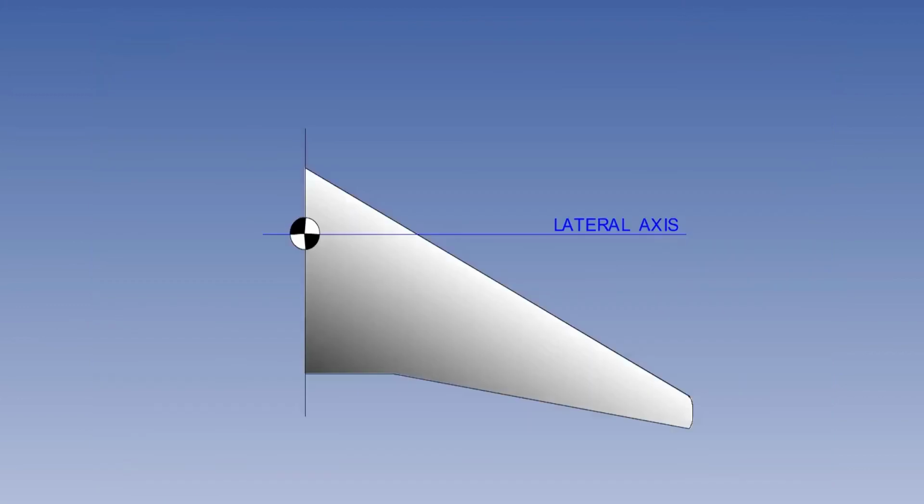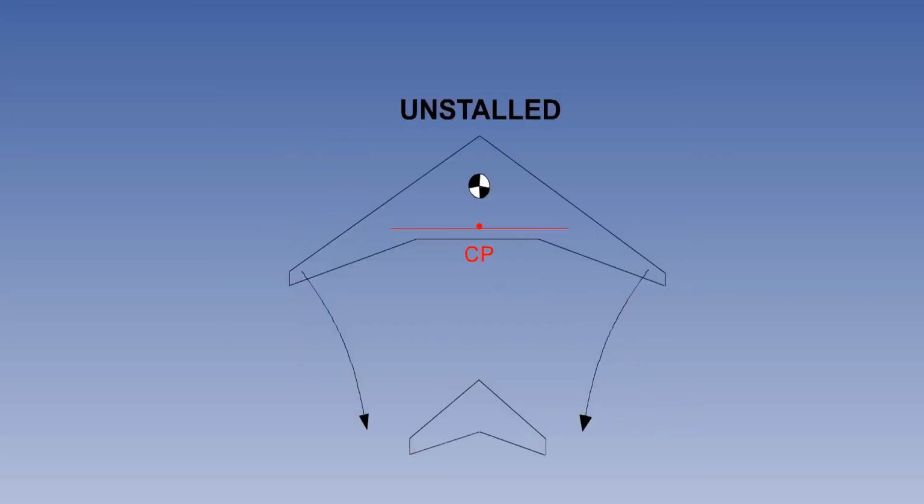A swept wing will allow higher maximum speed, but has a greater tendency than a straight wing to stall first near the tips. This loss of lift at the tips moves the centre of pressure forward and inward, giving a destabilising nose-up pitching moment. The lift is now concentrated inboard, and the maximum downwash impinges on the tailplane, adding to the nose-up moment.